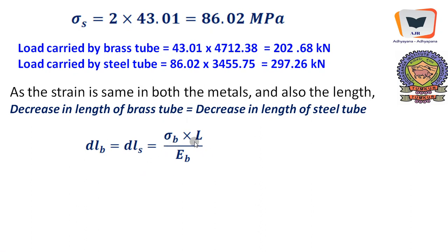Stress in brass tube into its own length, divided by EB. This is taken out of an expression we have derived in our second tutorial, wherein change in length of a member subjected to compression or tension equals PL by AE.